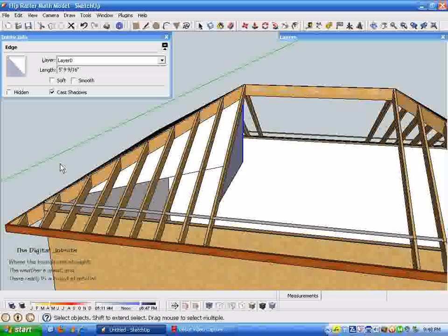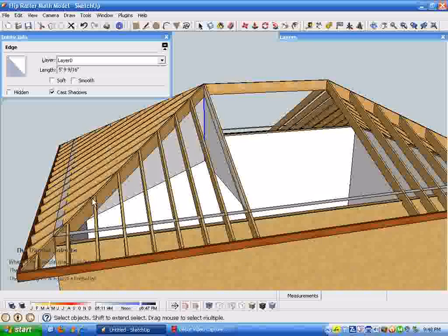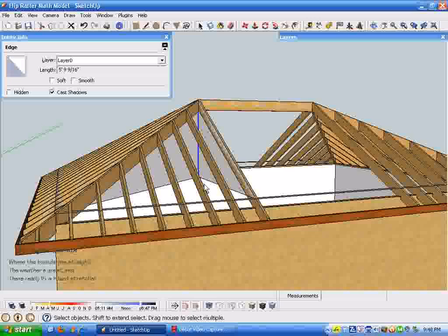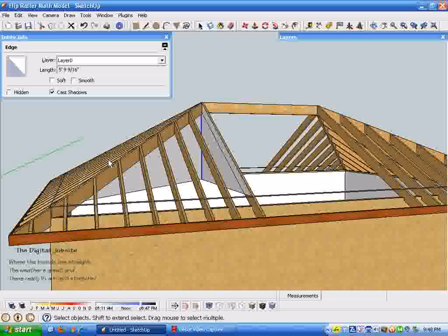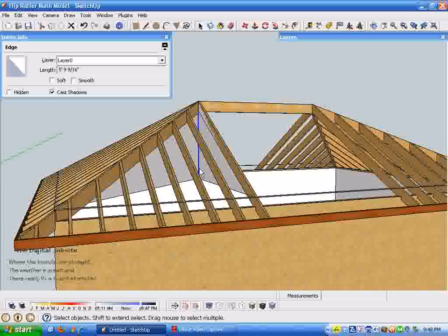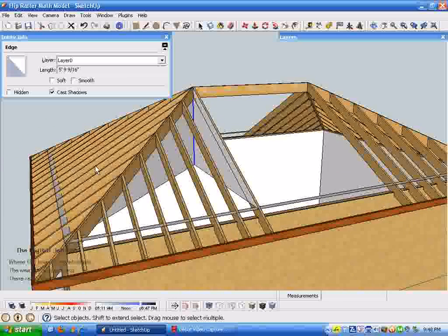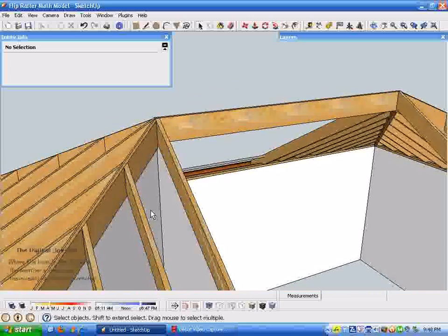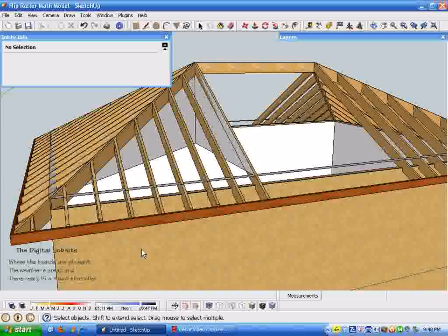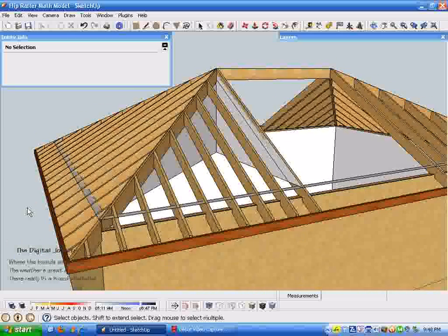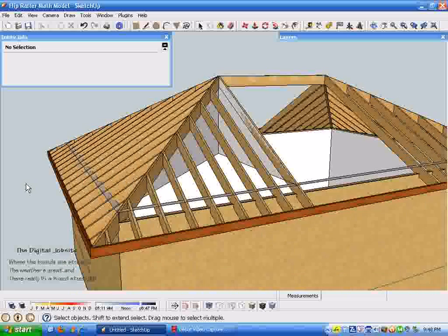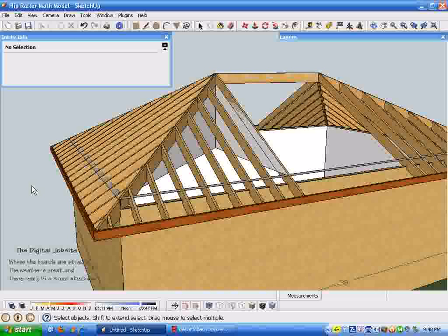and I'll put in the blog at finehomebuilding.com on the Digital Jobsite Blog. If viewers are interested in the benefits of using this method for doing off-angle hip roof framing, where the slopes of the two intersecting roofs aren't at the same pitch. In this case, they're 7/12 on both sides, but if you had a 9 1/2 12 on one side and a 6 on the other, all these angles become non-standard, and the centering of the hip rafter changes, the overhangs change, there's variables there, and when you start throwing those complexities into the framing, the model and measure method really starts to excel in providing the results you need for rafter layout.